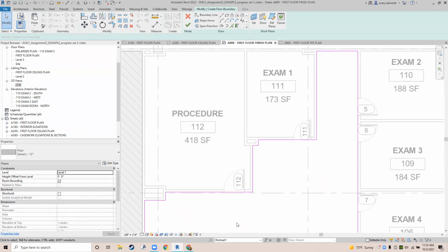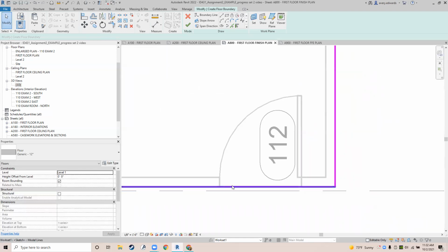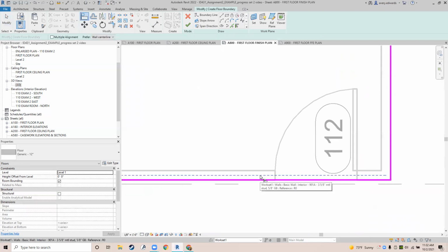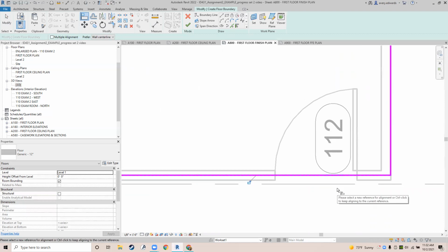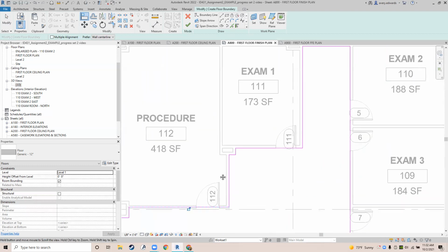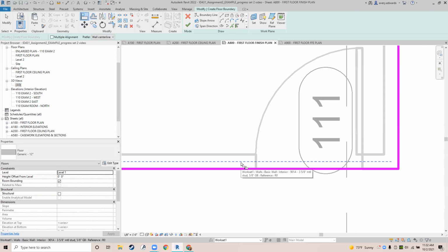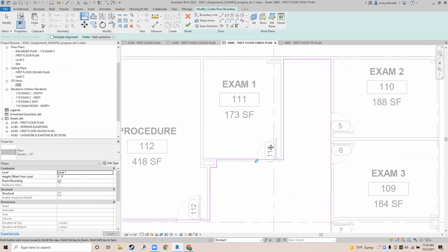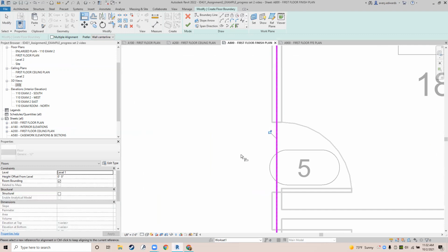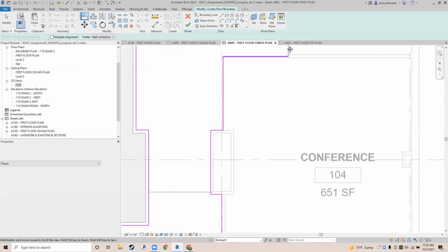Typically when you have a floor transition, you should take a look next time you're walking around your apartment or a building on campus. Take a look when you cross through a door where materials change. Best practice is for your material to change in the center of the door so that when the door is closed, you can't see where those materials meet. You want it to be centered under that door. So anywhere where we have a material meeting another at a door, we're going to use our line tool and put that line in the center, just like that.